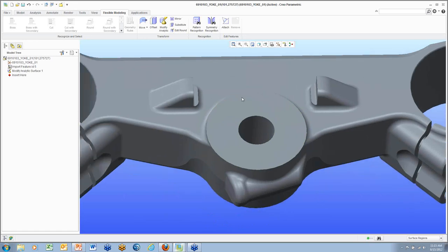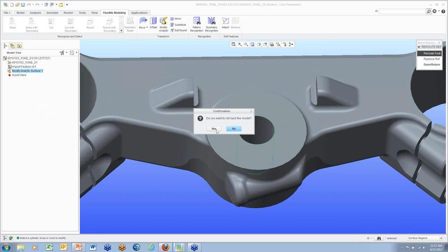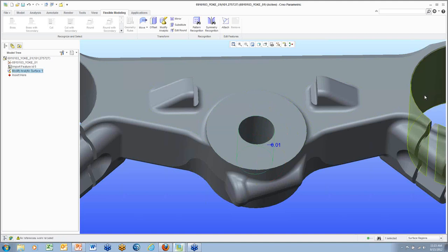So, when I opened this part up, I had simply a block. As I make changes to this part, the changes that I make will go into the model tree. Same thing happens in a parametric modeler. But I know in this particular case we are using direct modeling, which historically does not have a model tree. Nevertheless, all the changes that we make here are going to be listed in the model tree. We can simply right-click and edit the definition of these changes and actually go back in and edit them just like you would with any other parametric change. Okay, does that answer your question?